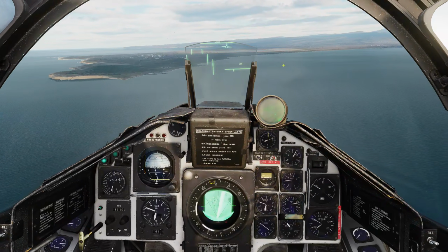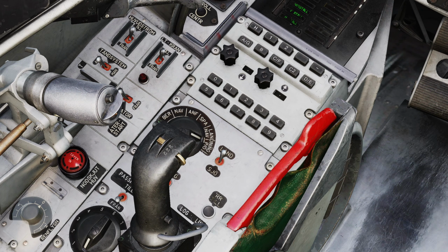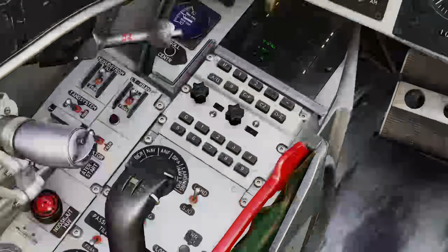And with that, we're actually going to go into the landing master mode. So master mode all the way to the right. I'm actually going to pause there. Note that on the master mode selector, there are in fact two landing modes. There's landing nav, which will put you into the instrument mode and turn on TILS, or there's the landing P/O mode, which is the visual approach mode. That's the mode we're going to use today.